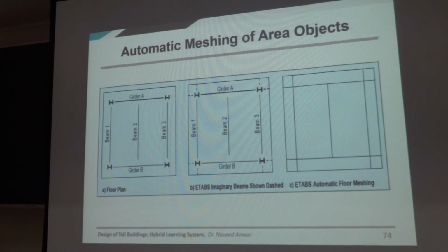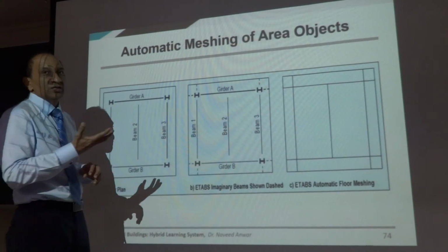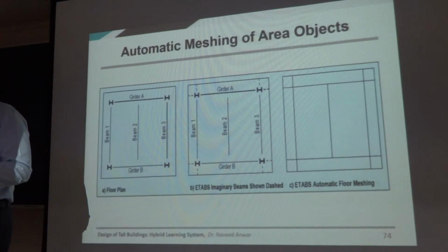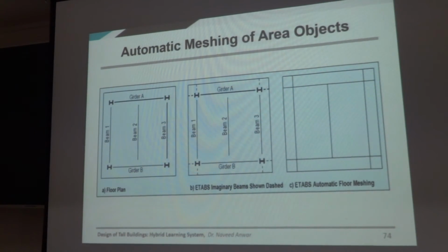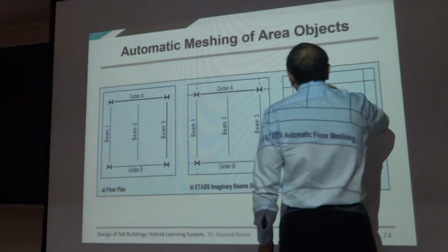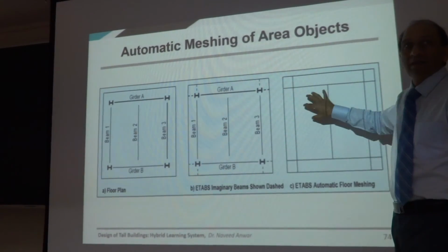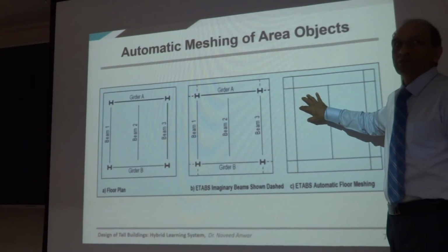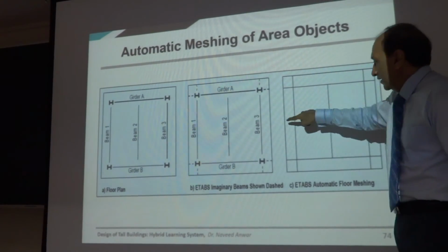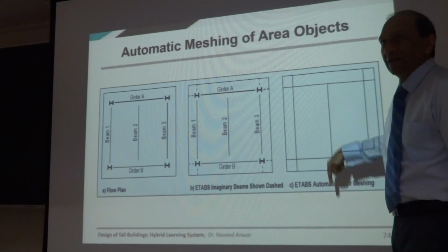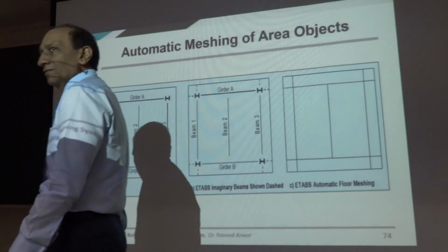It is to do with the deformation pattern and how many elements are required to capture that deformation. So if you deform something, you need at least 4 elements to capture the deformation. 4 this way, 4 this way. So each panel then must have about 16 or 25 mesh elements in between. So you tick, tick, tick, tick, tick, tick, and then you get the mesh, right?